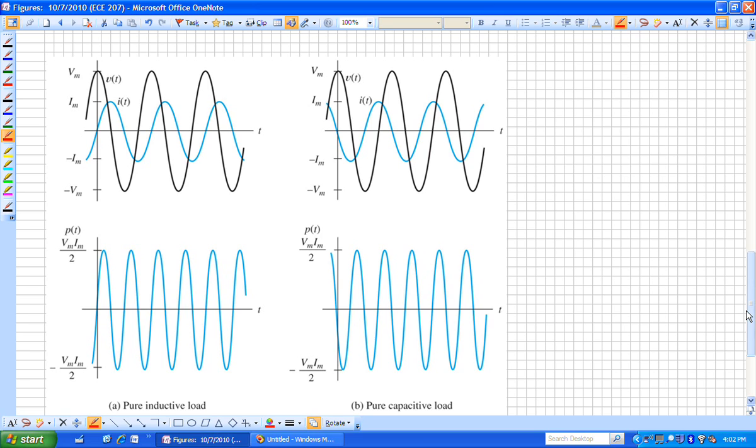On the left side, if we look at that, which one is peaking first? And remember, first is smaller values of time. So as we're walking to the right on that time axis, which one peaks first? The black curve, which is voltage. I hope this is consistent with what we said. I lags. So voltage leads current in an inductor.